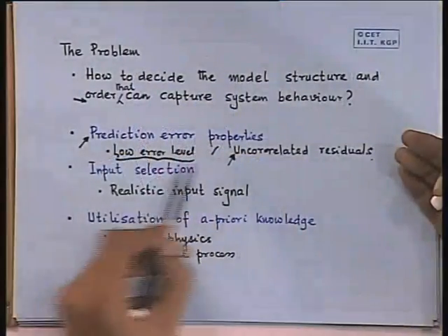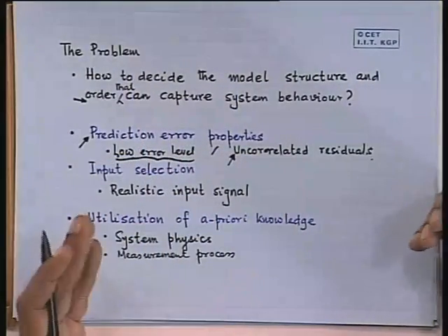So if you get residuals which are mutually uncorrelated and uncorrelated especially with the input, then you know that whatever residual you have does not contain any component of the input. So you have explained all the input. These are very important properties of the prediction error that you usually check to know whether you have extracted all the juice from the data. Whatever was due to the input, you have extracted into the model. Whatever remains is useless and has no connection with the input.